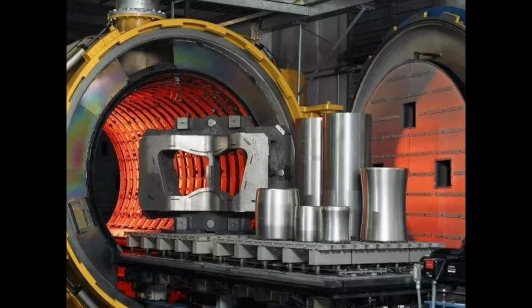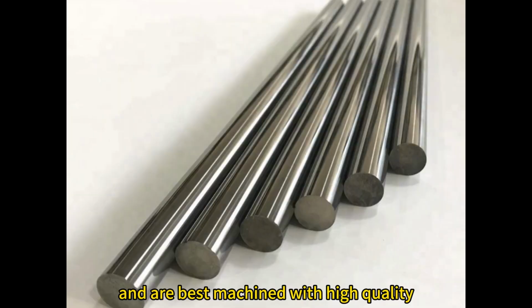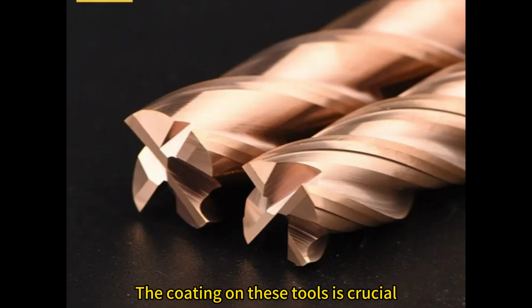Category 5. High-hardness materials, typically heat-treated to a hardness of around 45 HRC or even 50+ HRC. These materials require special attention and are best machined with high-quality ultra-fine grain carbide tools or cubic boron nitride tools, also known as CBN tools. Special reminder: the coating on these tools is crucial for their performance.